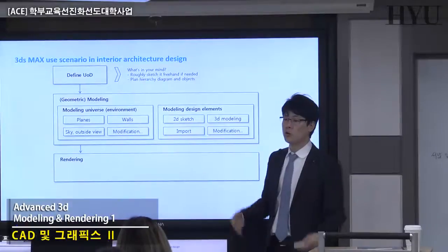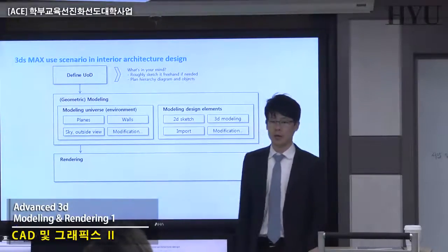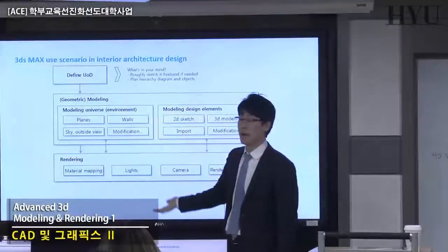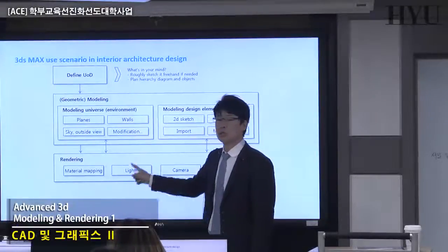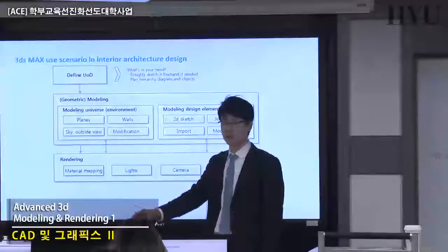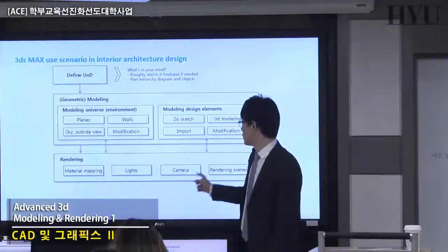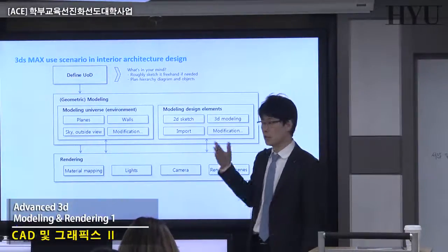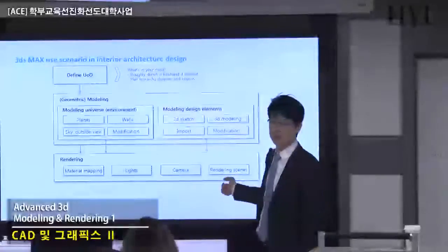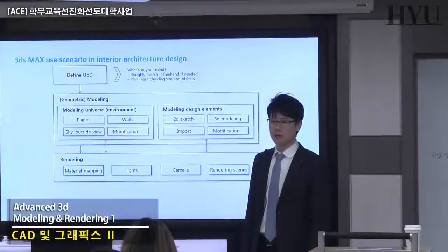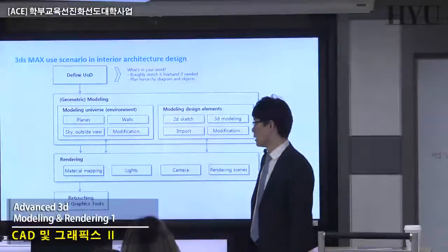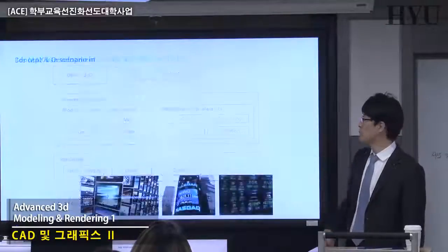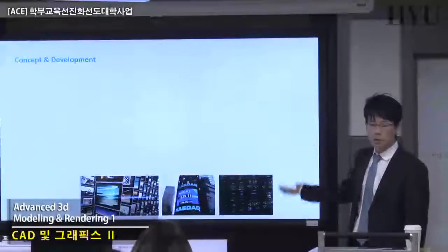And rendering, we already experienced the powerful mental ray. Thanks to mental ray's material mapping, there are hundreds of Autodesk materials, very high quality and well-defined, and photometric lights. Very easy to install, easy to control, but looking very realistic. Also, a powerful camera. You know how to control focal distance and some additional effects, including today's lab exercise. And simply render it. Then you can generate a very early phase, high quality image for your design representation and retouch in 2D Photoshop or others later.